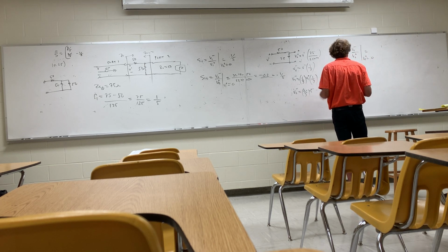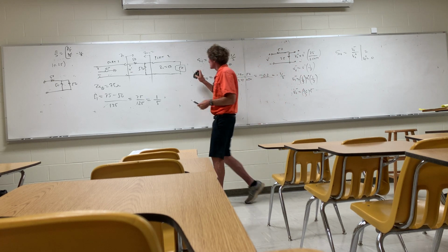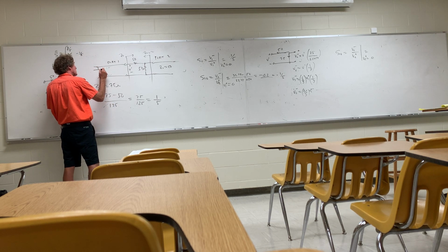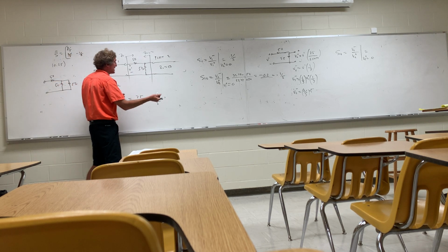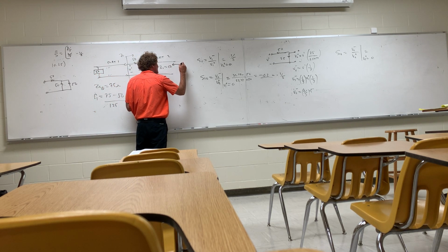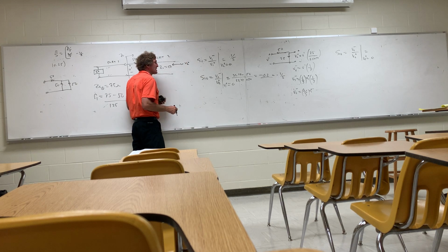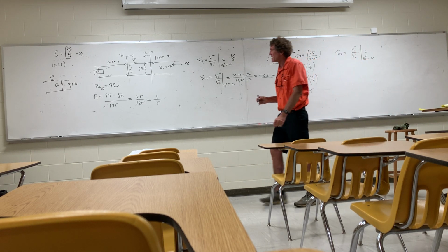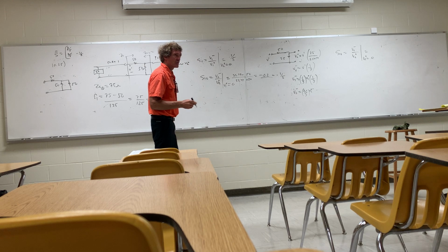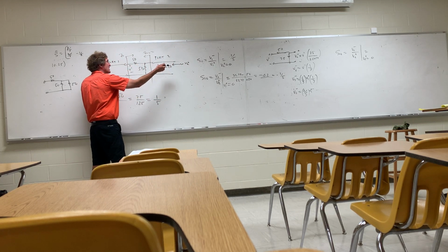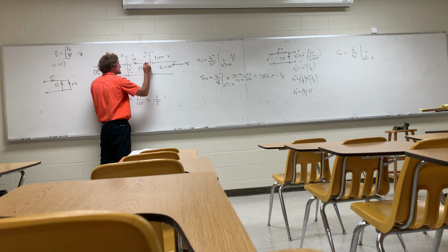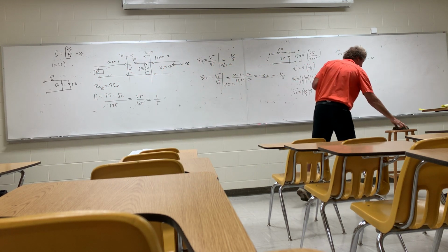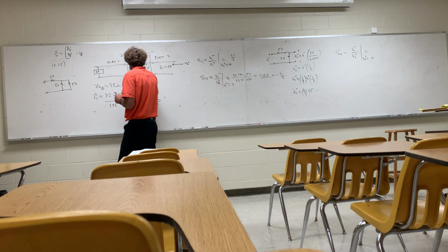Okay, so if we're doing this, now the situation changes and we look this way. Now we match this port with 50 ohms. And now we're gonna put a signal here. This is just a thought experiment. So this is V2 plus coming in, and we want to get S12. Think about what I really need. Got a wave coming in here. I need the voltage just on the other side, my V prime right there this time, don't I? I want to find how much gets across.